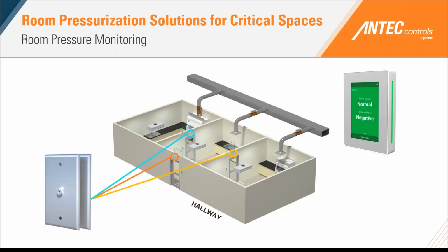So if we're looking at the same application for compound and pharmacy, in this sense, we have 3 pressure transducers utilized, both monitoring the pressures between and in reference to our anteroom. In this case, since we have 3 pressure transducers, we can utilize 3 pressure monitors.